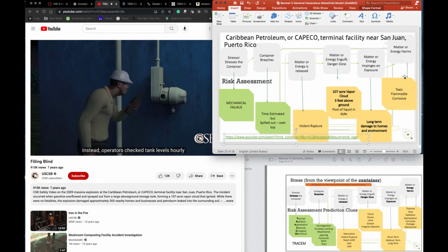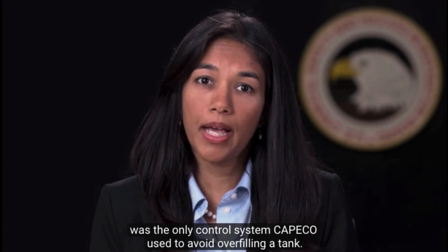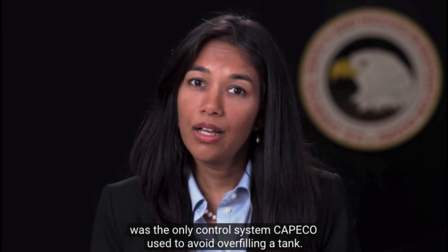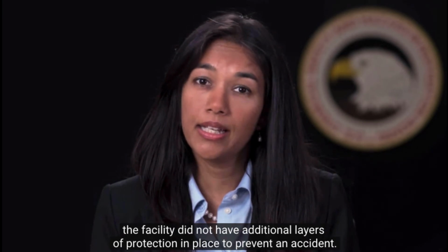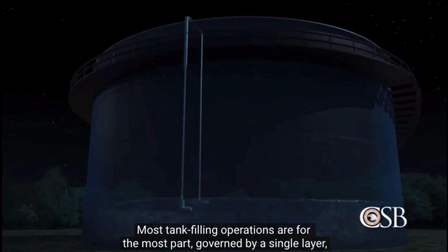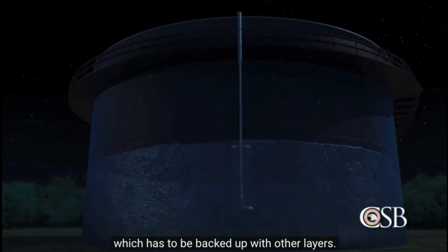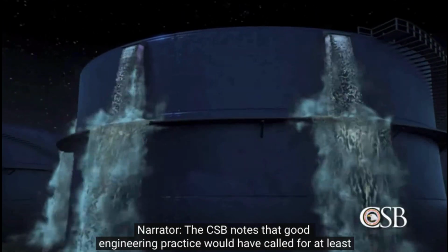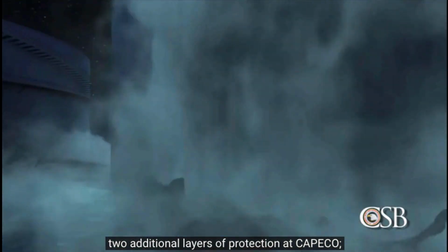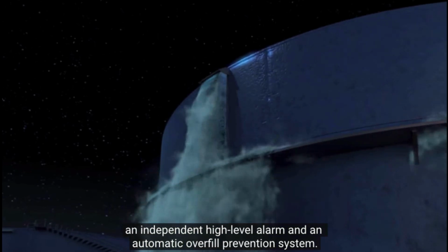Instead, operators checked tank levels hourly and manually calculated the time it would take for tanks to fill. This was the only control system Capeco used to avoid overfilling a tank. When that system failed, the facility did not have additional layers of protection in place to prevent an accident. Most tank filling operations are, for the most part, governed by a single layer which has to be backed up with other layers. The CSB notes that good engineering practice would have called for at least 2 additional layers of protection at Capeco, an independent high-level alarm and an automatic overfill prevention system.